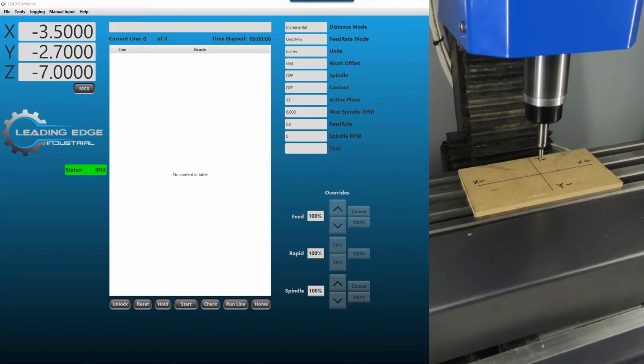We're going to start off using a wobbler edge finder, where we're going to set the upper left portion of the sheet you see in the picture, and we're going to set the lower right coordinate. We're going to use that as G54 in the upper left and G55 in the lower right. Then we're going to show you really quickly how to set your other coordinate axis. We're using just a really quick kind of move over, it looks close enough kind of thing. So if you want to just machine a quick part, you can set your 0 points that way. And what we'll do then is we'll swap over to a nice pointed tool and we'll set it off on the corners and show you how to do that. So let's go ahead and roll into this and get started.